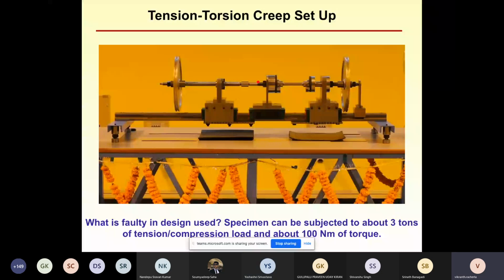See, the ball screw is rotating, but the column is not rotating, right? Column can only translate. So you need an element where the inner raceway, or the inner part, is rotating and the outer part is fixed. So the column is attached to the fixed raceway, which is the outer raceway of the bearing. In a structure, whenever you have a rotating element, it must always be supported on a bearing so that it will allow the rotating part to rotate freely and be supported on the stationary part. That is the purpose of a bearing.